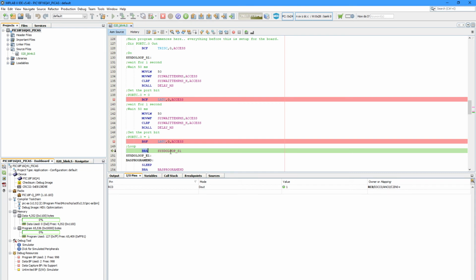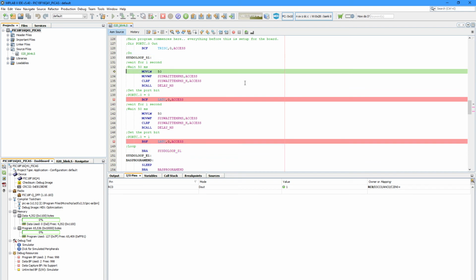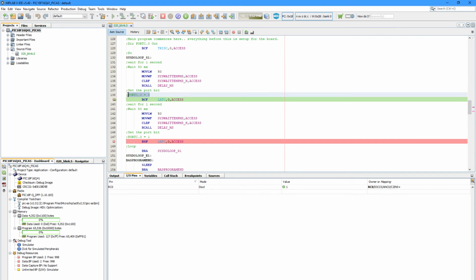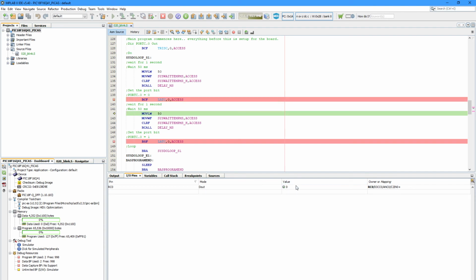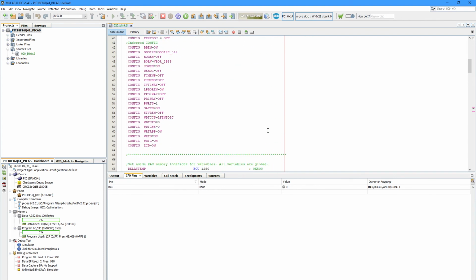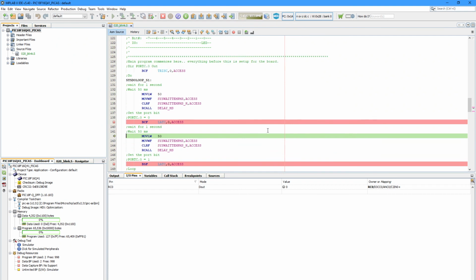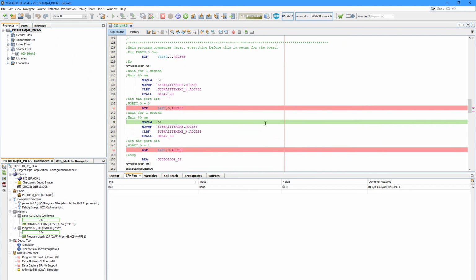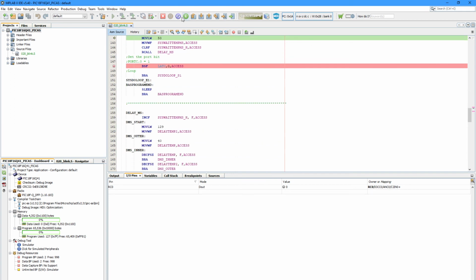Now it's going to branch back to sysloop 1, which is our do loop. Then it's got a delay, and then it says port C0 equals 0, and if I press F7, it will toggle. You can now examine the complete code that's been generated by GreatCow Basic, but in this particular case of the Q41, we are using PIC-AS to generate the hex file. It works absolutely fine, and you can learn exactly how GreatCow Basic works.